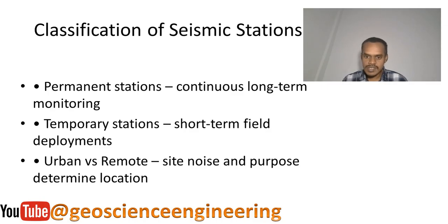And the other type is strong motion stations, which are generally installed in places where there are industries and a huge number of people, like population. These are used to record large ground accelerations, and they are used in engineering seismology to improve the building codes and the designs.